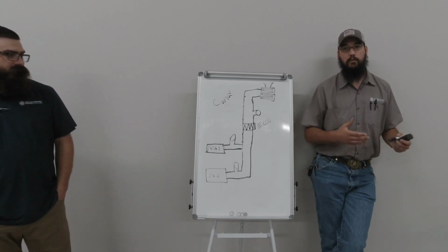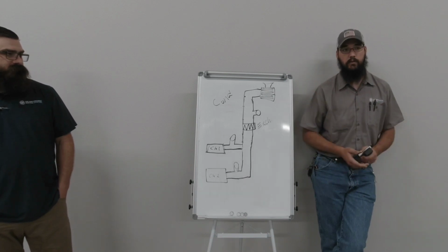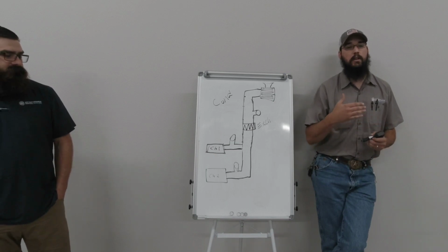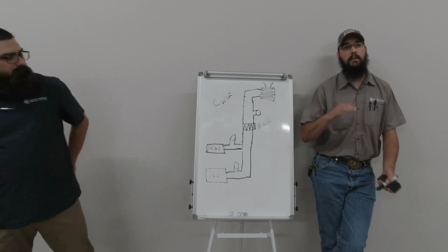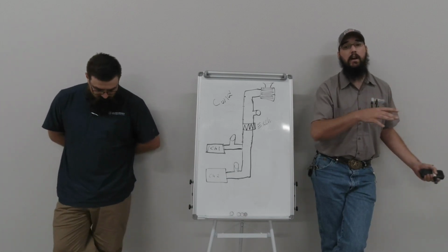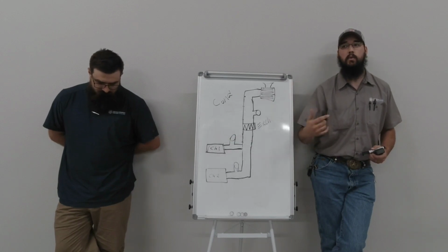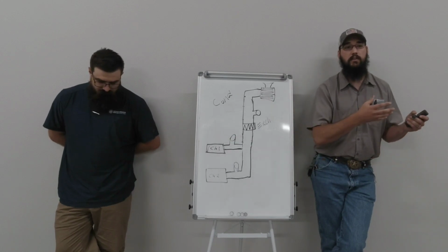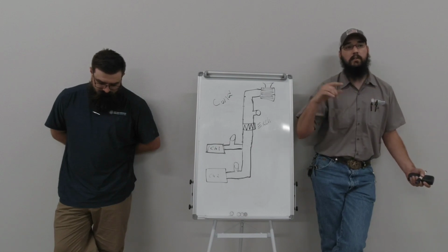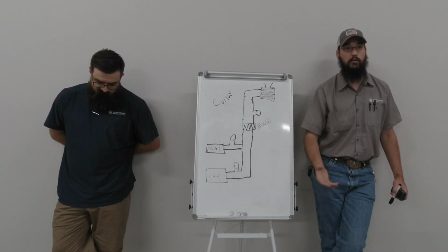But the chances are, if you're doing that at each unit, then you factor in my cooling tower, for example, or even my boiler, for that matter, is now trying to work even harder as well, because it can't get its differential since all the equipment has too much flow inside. That probably means your tower itself has too much flow, which means it's working extra hard to try to achieve the same deadband, right, that it can't achieve because it's not able to have the water there long enough to process that heat back out of it like it's supposed to.